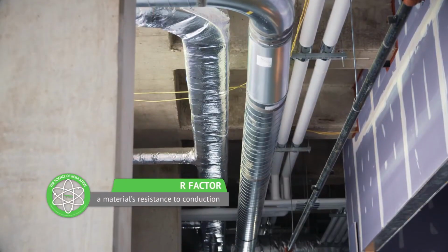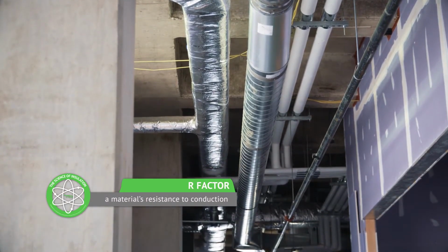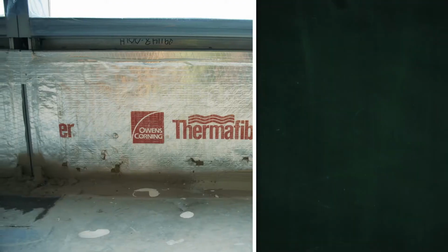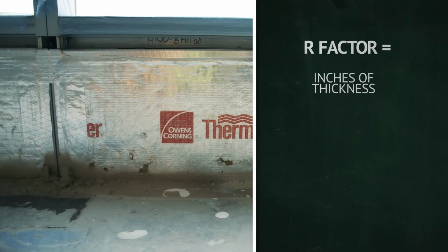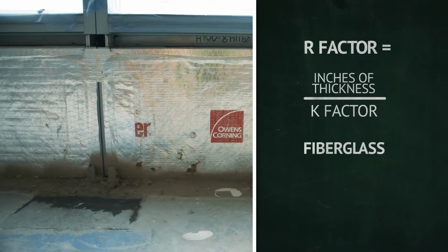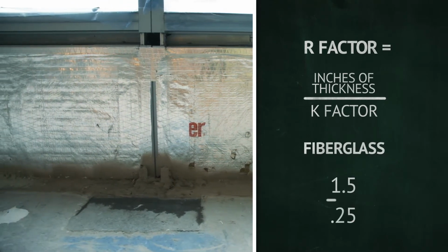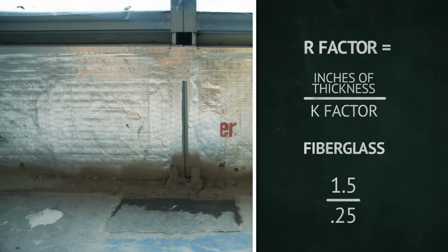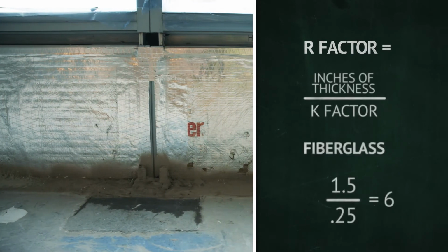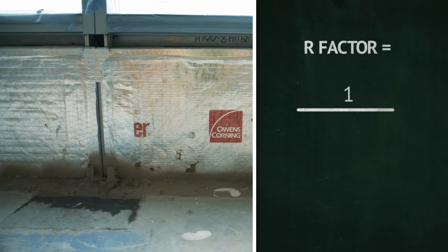The R factor is how much a material is resistant to conduction. There are several ways to determine the R factor. If you know the K factor of a material, you can use the following formula. R factor is equal to the thickness of the insulation divided by the K factor. An example would be for fiberglass that is 1.5 inches thick. We know fiberglass has a K factor of 0.25. Therefore, 1.5 inches divided by 0.25 equals an R factor of 6. If you know the C factor, the R factor can be calculated by taking 1 divided by the C factor.